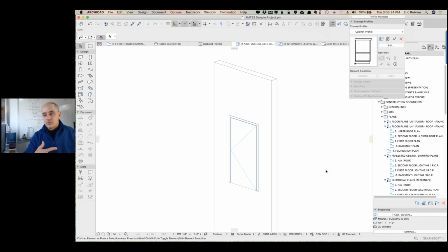Now, if you have walls of different compositions, I would say you have 2 main choices. One is you can make the wall out of a complex profile, so maybe it's stone at the bottom and brick above, or some other detailing that happens, and so the door cuts in through both because it's one wall. Or if you do have stacked elements, then you can cut an extra hole in the one that doesn't have the actual door. So hopefully that answers that.